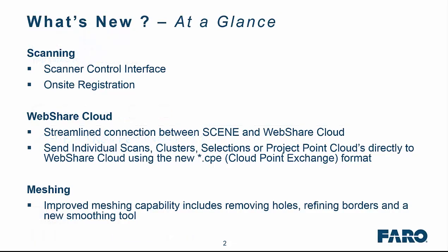Firstly, we'll look at some of the basics at a glance. So we've now given you the ability to control the scanner interface directly within Scene. And also we've included a new on-site registration functionality, which I will cover in another tutorial. With regards to WebShare, we've streamlined the connectivity between Scene and WebShare, where we can now send scans, clusters, selections, or project point clouds directly to WebShare using the new Cloud Point Exchange format. Again, I've split this out into another tutorial so we can go through that in more detail.